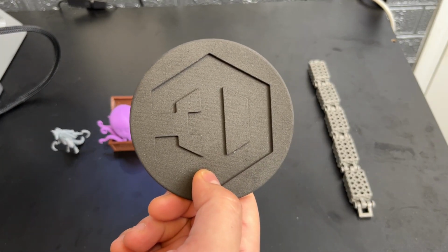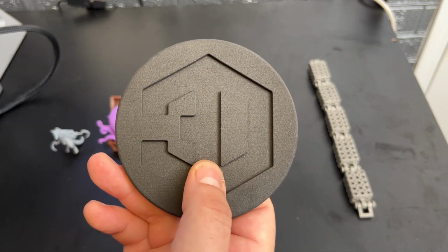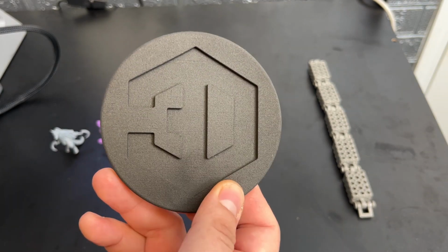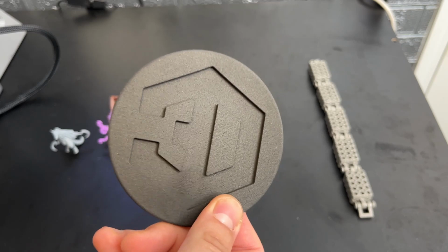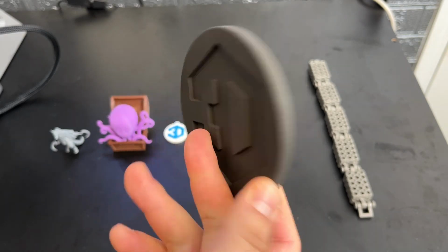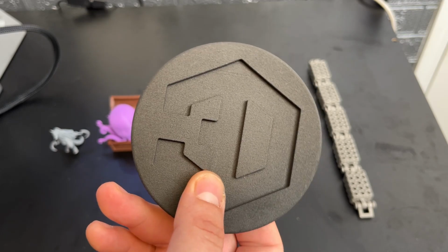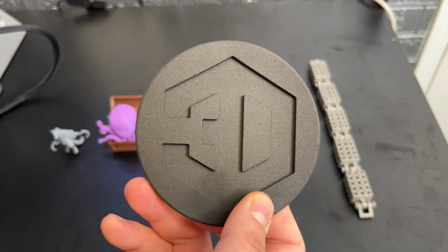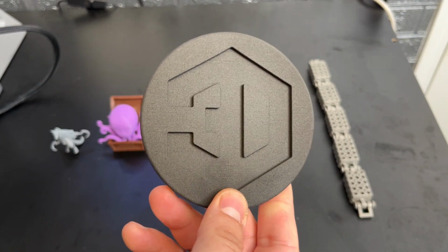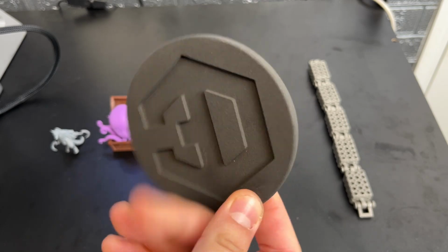And it's high strength, best for load bearing and functional parts. The materials that are used are nylon powder, glass-filled polyamide, and metals, although I've only seen it in nylon, and that's what JLC 3DP offers. This is in nylon over here, and this produces durable parts without the need for support structures. Excellent for complex assemblies and high temperature resistance.